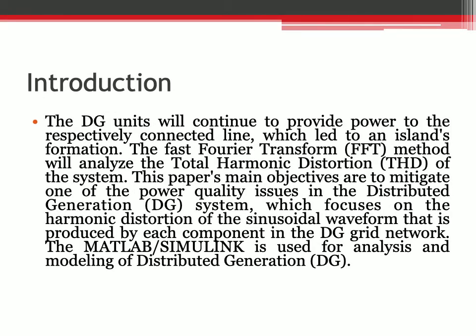The DG unit will continue to provide power to the respectively connected line, which led to islands formation. The fast Fourier transform (FFT) method will analyze the total harmonic distortion of the system.